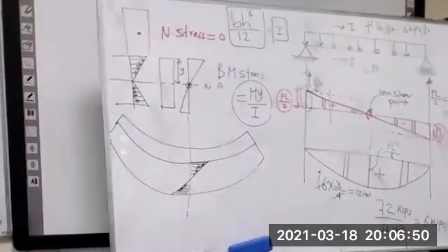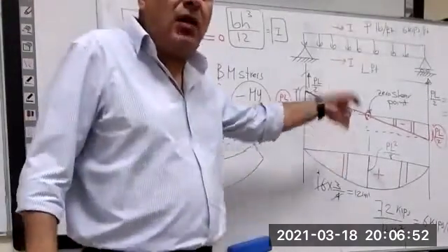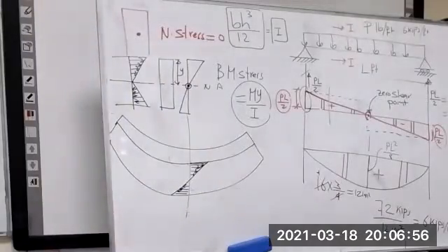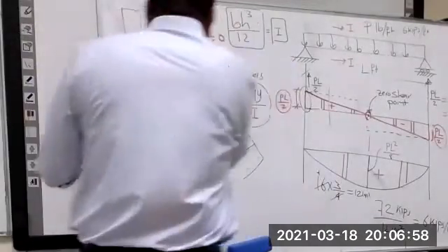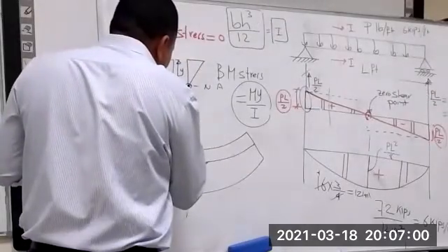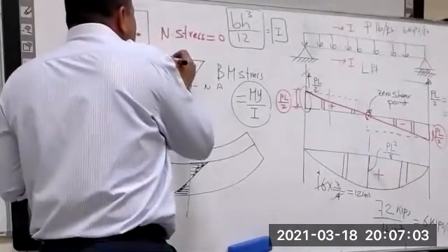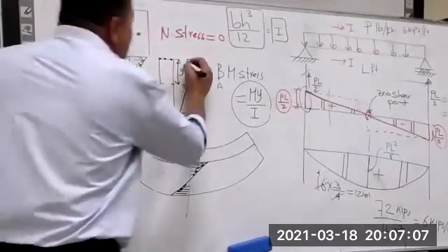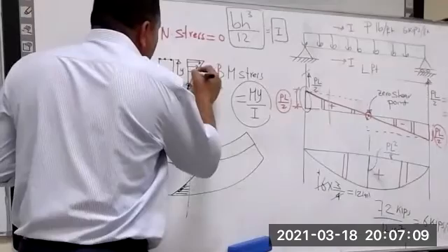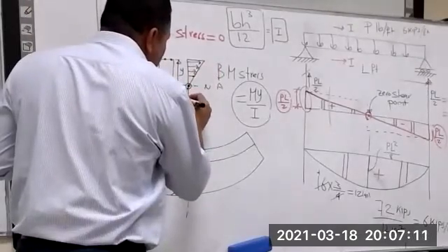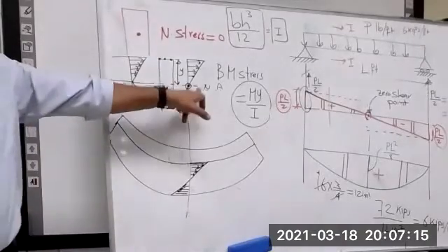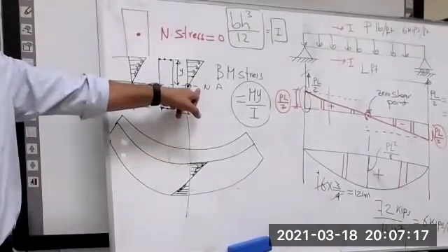At the neutral axis, in the center of the span, it is equal 0. The maximum is at the edges, the lower fiber and the upper fiber. This is the tension, and here is compression. Neutral axis, always zero flexure stresses.